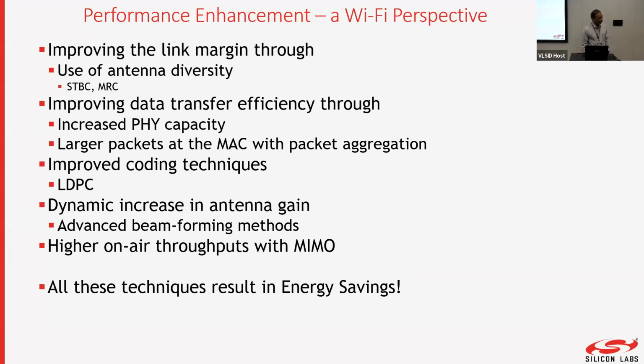When your receiver uses two antennas, it is called combining, or MRC, maximal ratio combining. You can combine signals from two sources and average them. And you know what is the average of noise? Average of noise is 0. The more you average noise, the more you can eliminate it. The more copies of the same signal you can get, which is impacted by random noise, and when you combine them, the higher will be your signal to noise ratio.